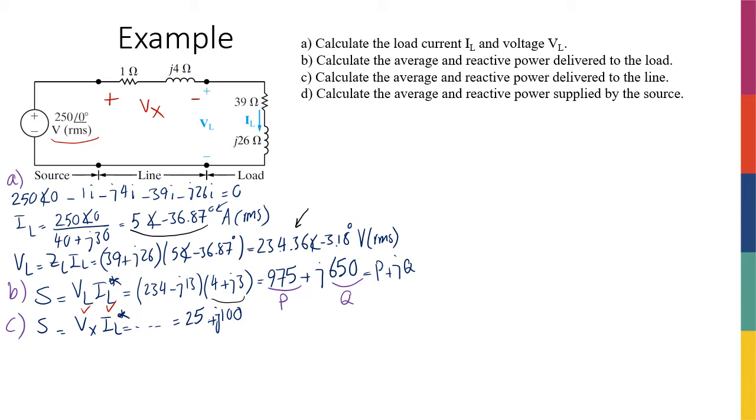The other way to do this is that if it was only resistors, we knew that, well, since I have the resistance and I have the current, I really don't need to actually calculate the voltage to have the power, because we knew that for resistors, P was equal to VI, and it was also equal to RI squared, because V was RI, and it was also equal to V squared over R, right? Now I wonder, here I don't have a resistor, but I've noticed that everything that applied to resistors kind of more or less applies to impedances. So I have a Z. So can I say it's basically ZI squared and V squared over Z? Well, we have to actually dig deeper into this.